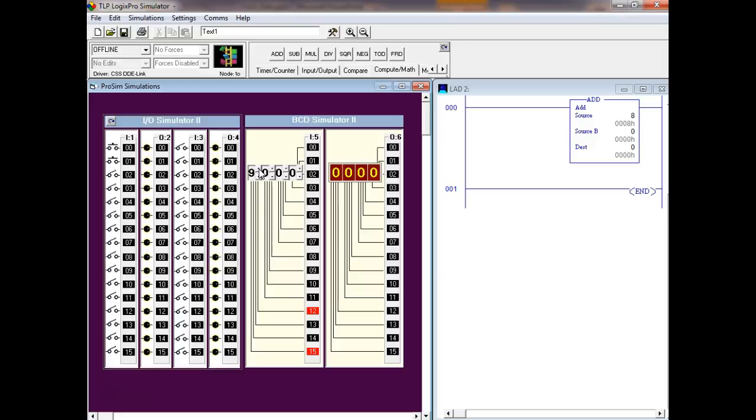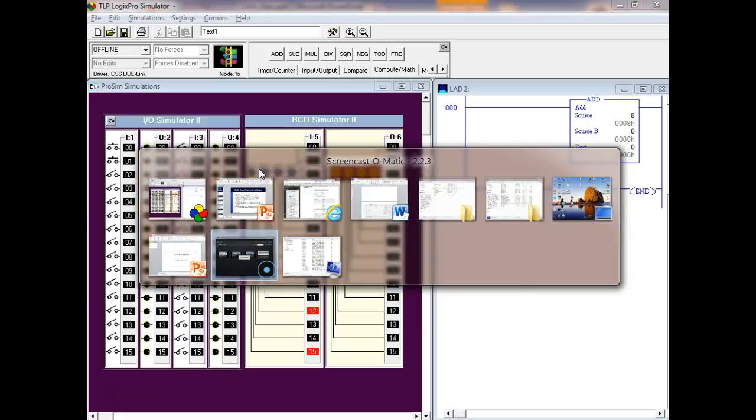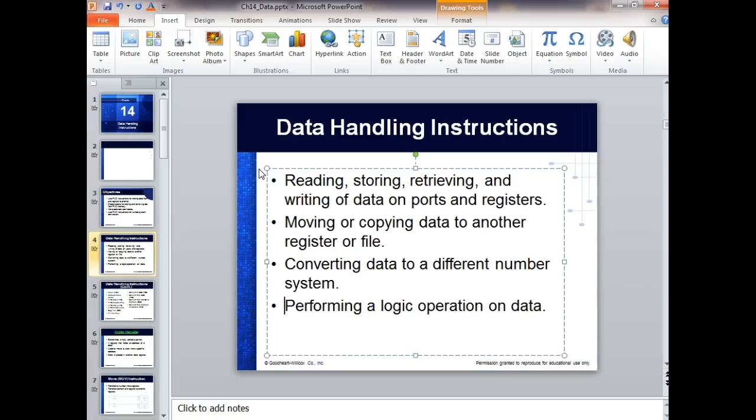So most of your digital outputs, you got displays on a PLC that tells you the speed of the motor or the counters or stuff like that. It's probably going to be BCD, right? If I input a thumb wheel switch, because an operator, odds are, does not know the hex numbers. They know what numbers it is. Definitely. So converting between these different bases and these different codes, we need to have the ability to do that in our PLC.